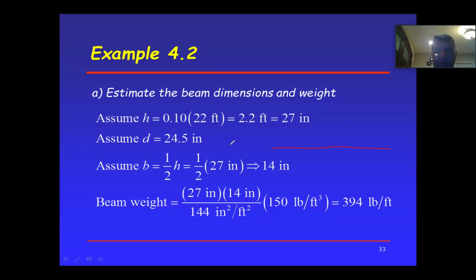Okay, there we go. So there's the beam. I will take the depth of it times the length times the width. That's going to give me cubic feet. I multiply by 150 pounds per cubic foot, I get pounds. But I don't want pounds. I want pound per foot along the beam, right?